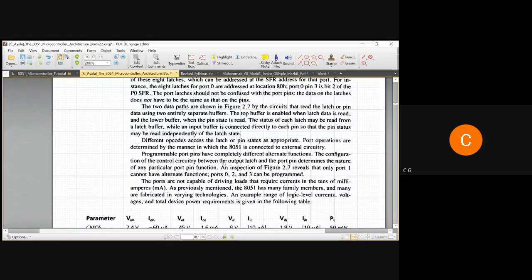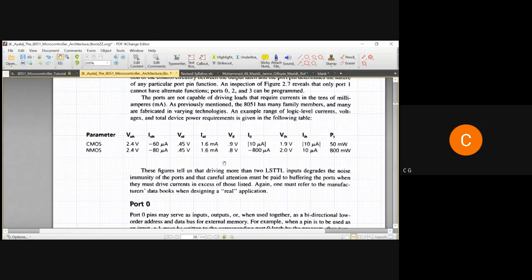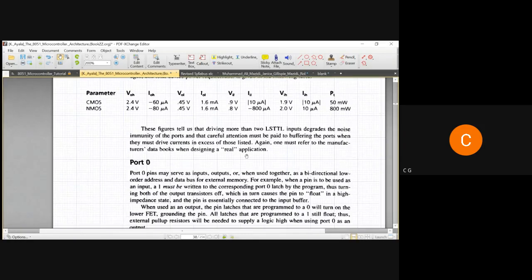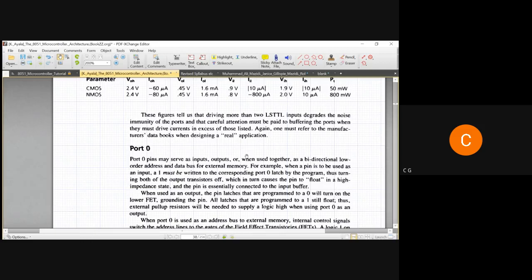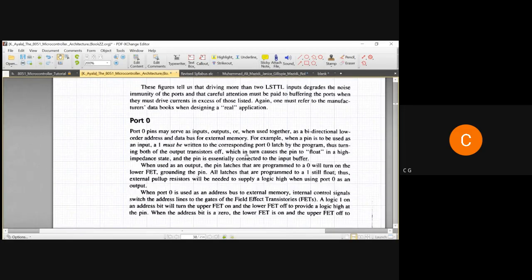Until the next clock pulse comes and the D latch is enabled, the data will not be transferred. So it is acting like a temporary register, where you can store some number, some 0 1. But to employ all this facility, you need to understand how to program the 8051 and utilize it for your better purpose.